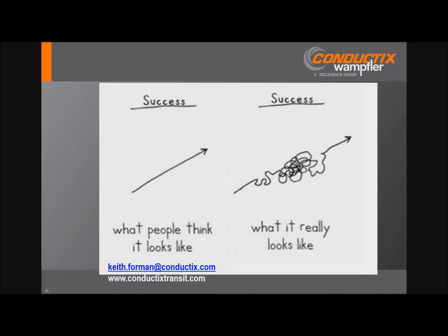For example, in the Las Vegas monorail, where you have a fairly wide collector shoe, in fact the collector shoe that I showed with that deep groove, they vary the position of that conductor, snake that conductor, to get good even wear, and it gives you much greater shoe life. So yes, it's advisable. As a general rule, variation of movement is within 2/3 of the total length of the shoe.